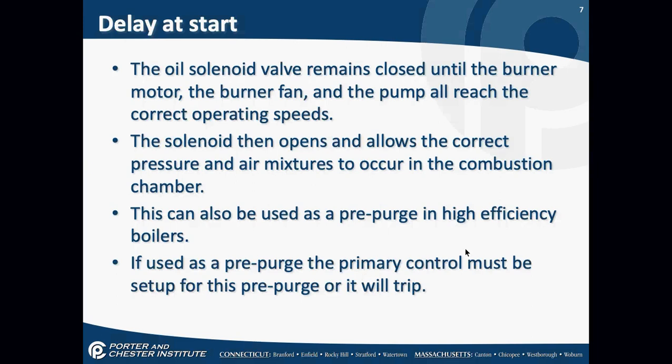If used as a pre-purge, the primary control has to be set up for this. There's an extra wire specifically on the primary control for the solenoid. A lot of times it's purple. There's an extra wire.